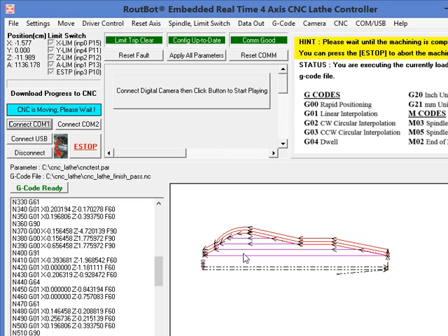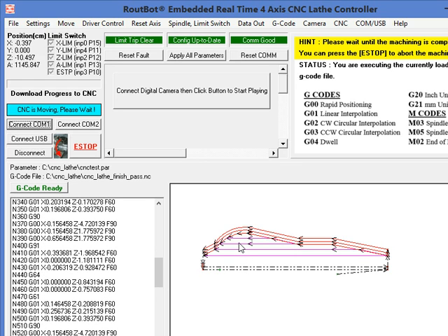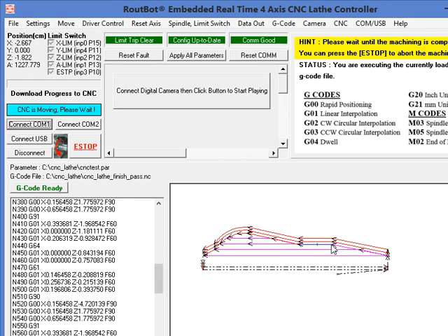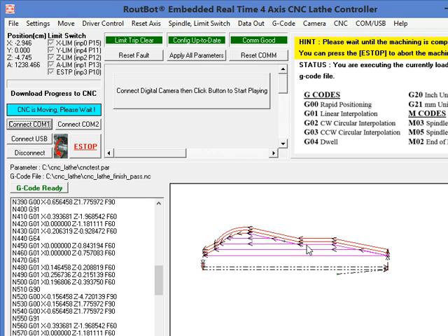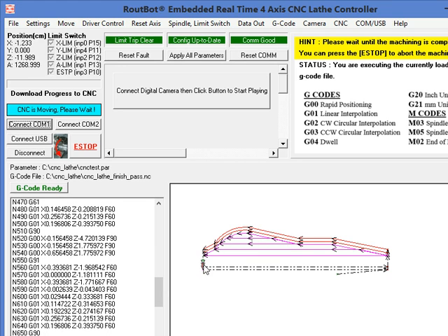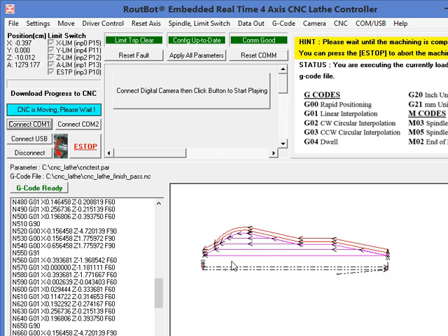Right now, it has already done 1, 2, 3, 4 roughing passes, and it will do the very last roughing pass, which will bring it all the way over there. So now we follow the CNC cutting tool head doing the last roughing pass, and we can see that those two are the finish passes. Because of the finish passes, the profile was offset by the number of finish passes to give you all the roughing passes. So now it did all the roughing passes, and it removed all that material.